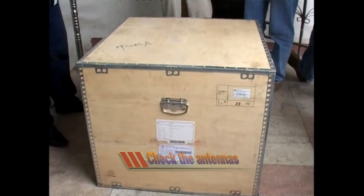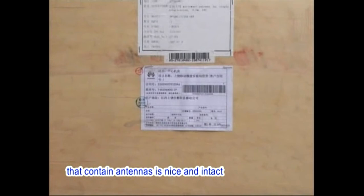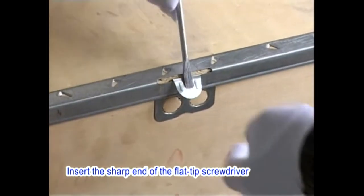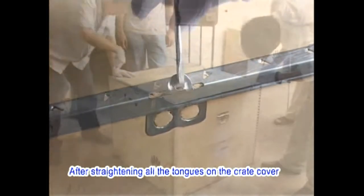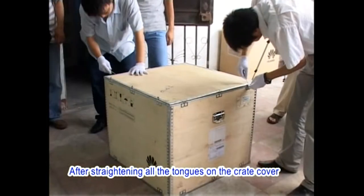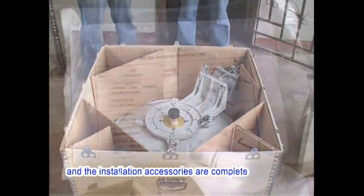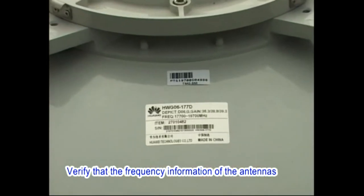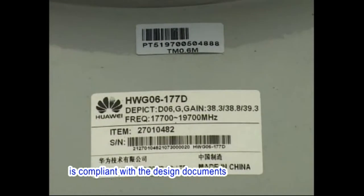Check the antennas. Check if the appearance of the packing crates that contain antennas is nice and intact. Insert the sharp end of the flat-tip screwdriver into the hole of the tongue and straighten the tongue. After straightening all the tongues on the crate cover, remove the cover. Verify that the appearance of the antenna is intact and the installation accessories are complete. Verify that the frequency information of the antennas is compliant with the design documents.